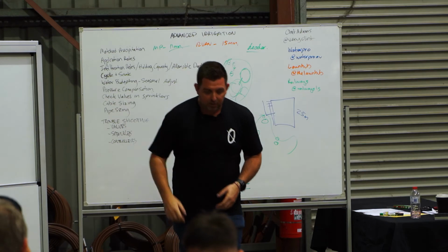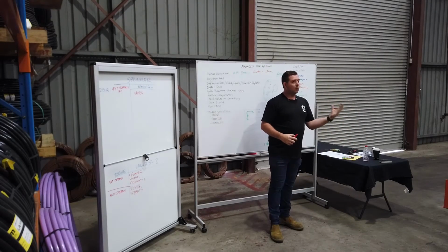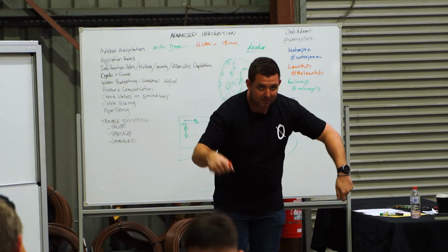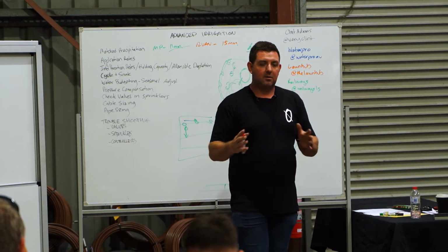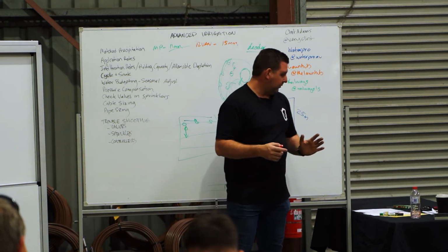The problem is with sprinkler systems, the initial startup requires more water than the operating flow. So if you go out with a situation like that, you'll pull the sprinklers up, you'll actually get them to come up and they'll stay up. There's a thing called flow-by where the sprinkler shaft is tapered.